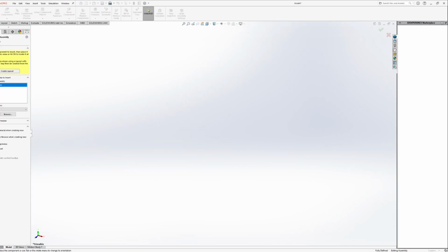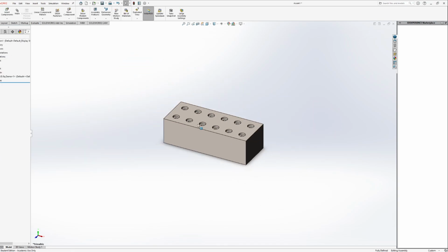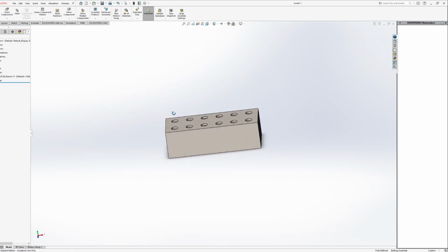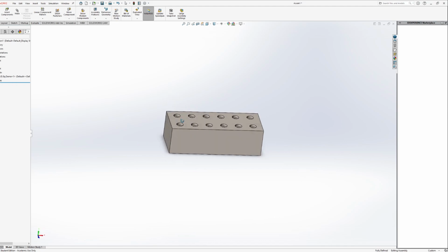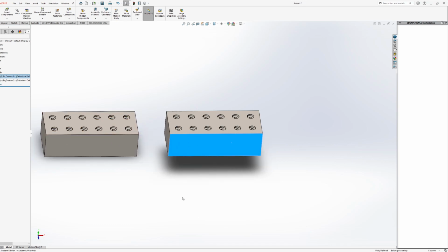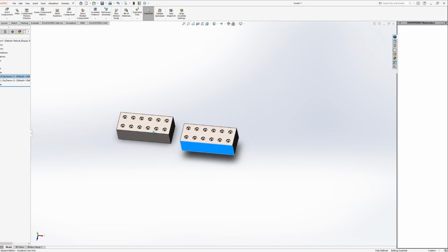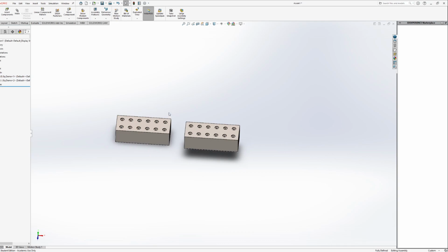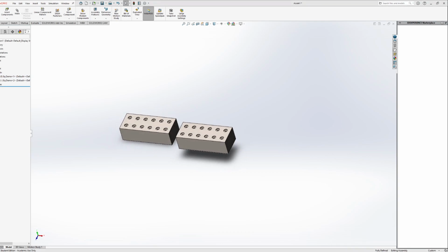Okay, good. A nice little pro tip, if I haven't said it already, or if anybody hasn't figured it out: if you hit Control and then left click on an object and pull away, you can duplicate it. So if you have several of a specific part in an assembly, it's a very good way of creating more of that specific part.